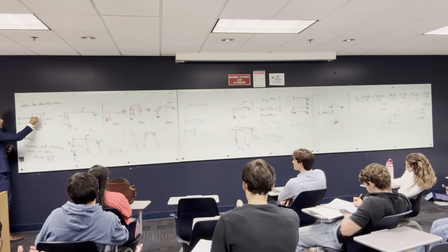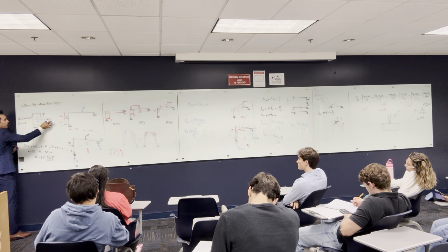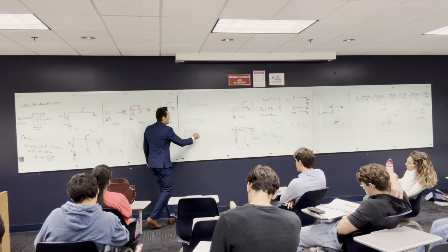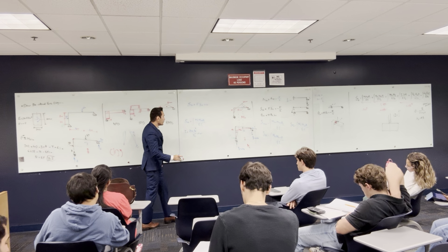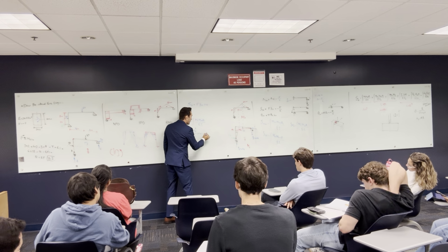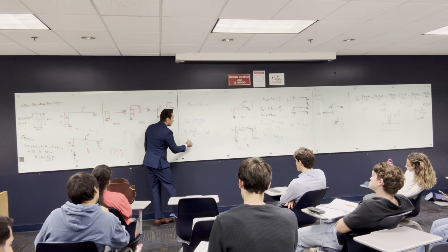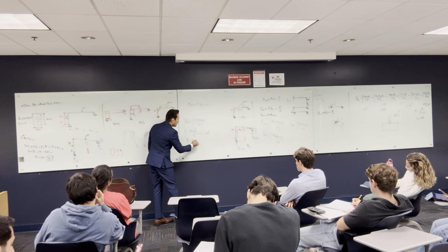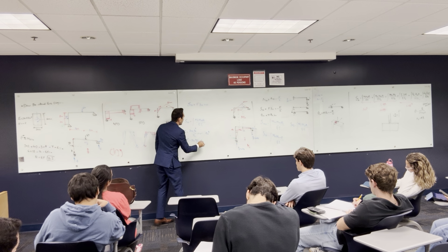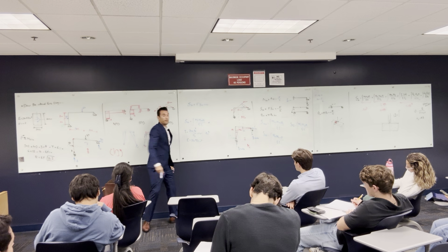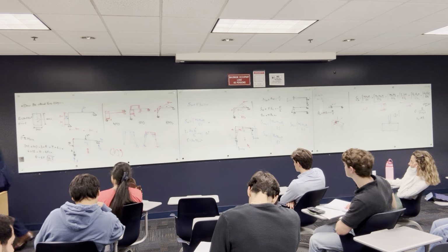If I want to find the other axis, it's going to be 40 times 20 to the power 3 over 12, and then you find this value. And pay attention, this is all in centimeters, so at the end you're going to have centimeter to the power 4. And E is equal to 210 ton per centimeter squared, so everything is going to be in ton centimeter. Once you solve this, you are going to find delta 1O.